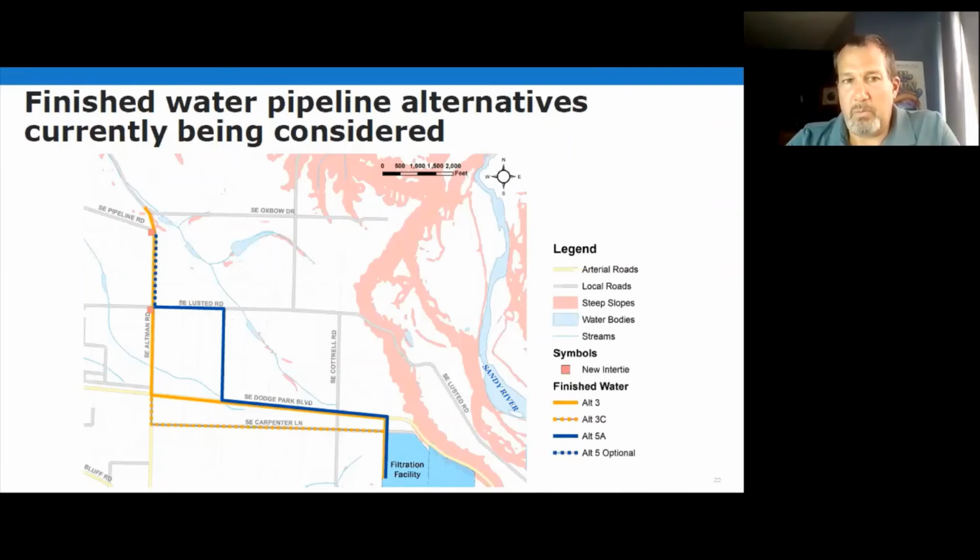It's going to be a pretty major road improvement down all the way to Altman. So the right-of-way width there varies between 30 and 60 feet. And so we would look at getting some temporary construction easements to get it in. We would plan on putting back what's there. Obviously, it would be new road surface, with a base under it and asphalt. As far as what the width would be and curbs and sidewalks, we're looking for input here.